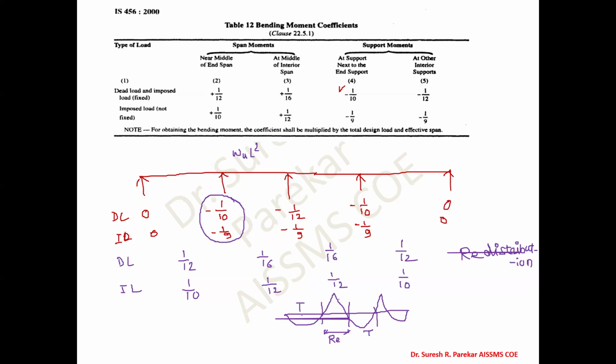So our capacity is very large in this region where we have T beam, and load coming on it is lesser compared with support. So what we are going here, as at support we have rectangular beam, we are going to reduce the moment at support, and transfer it to the span moment.